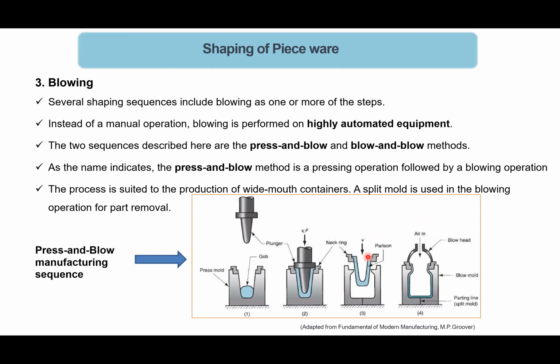Sometimes with this process, at the first step, if the temperature is too low, then it becomes solid. Then if you blow air, it will not expand and stick to the mold surface. In that case, we need secondary heating of this conical structure. Okay, did you get it?